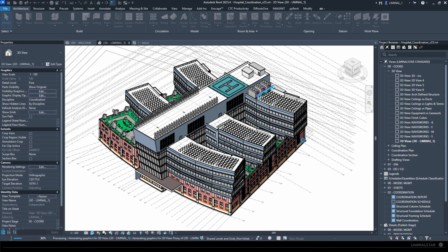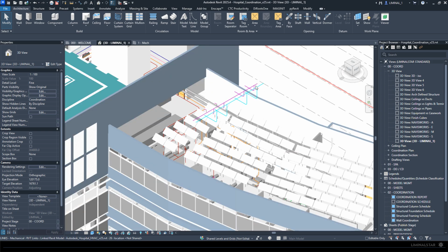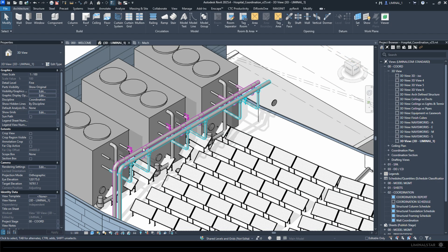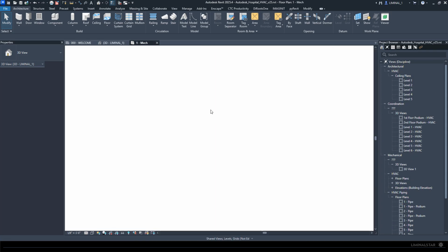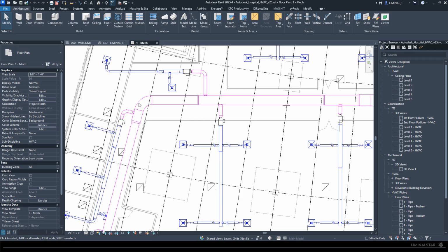Okay. So now I'm just back to any old default view with the settings, but if you zero in over here, you can see here's some of that mechanical modeling, and it's got these highlights to it that, I don't know, if you're not in a mechanical discipline, you might be like, why is that cyan? Why is that magenta? So if we come back over here, we can take a look at that in this mechanical model. And it's not like they said make all these ducts magenta and these ducts blue, and they did an override on them. This comes from the system.